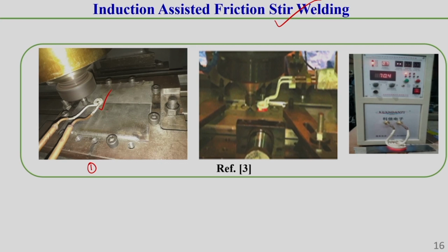Now, once this eddy current passes through the workpiece zone, as the workpiece has some resistance, heat will develop when current passes through this resistance. That is very well known to you. Let the workpiece have a resistance R, and let the eddy current be I. Then the heat energy will be I squared R times T, where T is time, in joules. We know how I squared RT comes about: the power due to current flow is V into I, and V equals I into R.